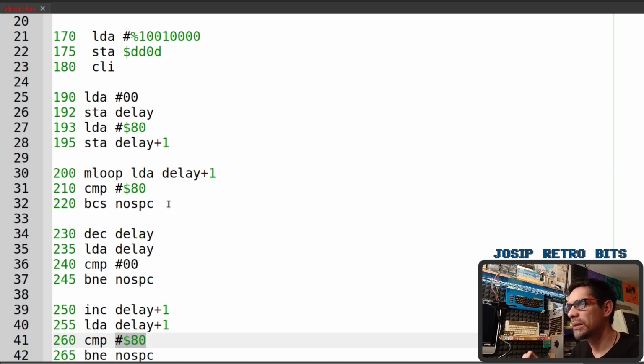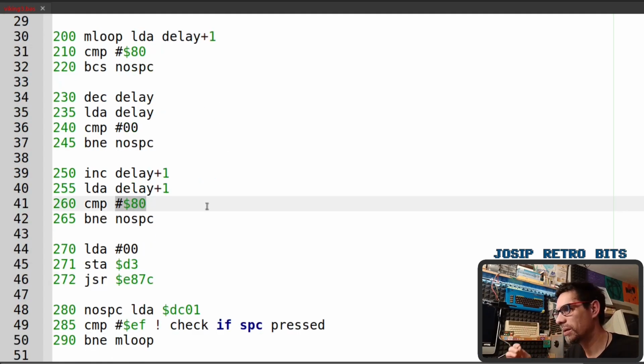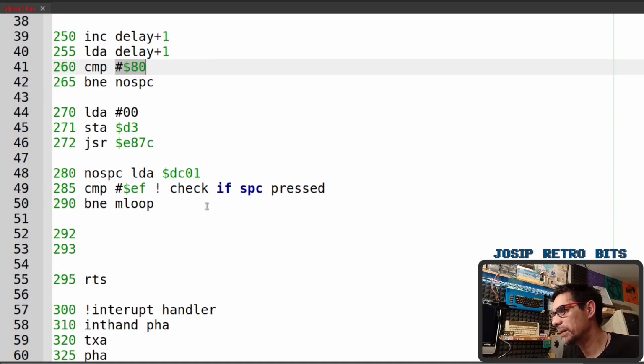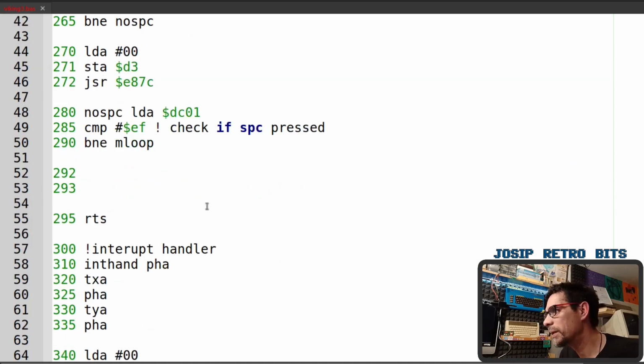So this timer will be constantly reset as long as we receive new signals. Once we stop receiving those new signals, our counter will continue to count. It will eventually reach 8000 hex and it will produce new lines. So that's basically it. Maybe I could do this in some different way, but this makes sense to me.